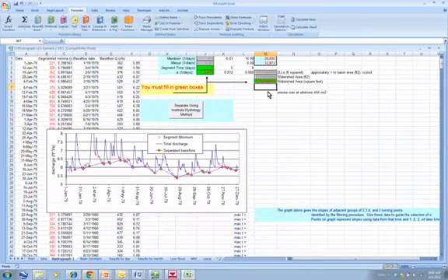So you do whatever conversions you need to do, but it has to be in units of square feet. This is the segment time here for partitioning up the hydrograph, and something in the range of 4 or 5 days up to maybe 8, 9 days generally works. And then this is the basin constant, and there's another couple of worksheets to give you some ways to estimate what the basin constant should be.